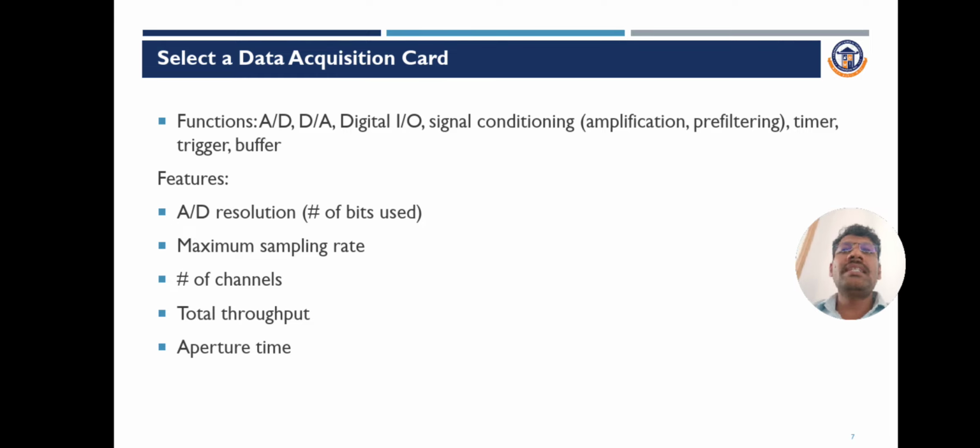So these functions are taken as basic elements, which are determined by their functioning rather than their construction. For the primary sensing element, the quantity under measurement makes the first contact with the primary sensing element of a measurement system. In other words, the measurement is first detected by the primary sensor. This is immediately followed by the conversion.